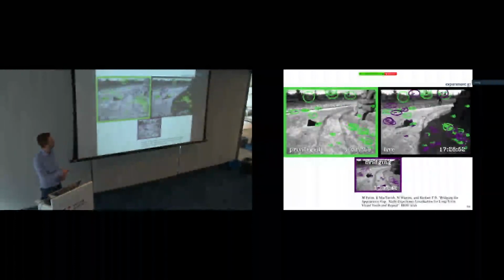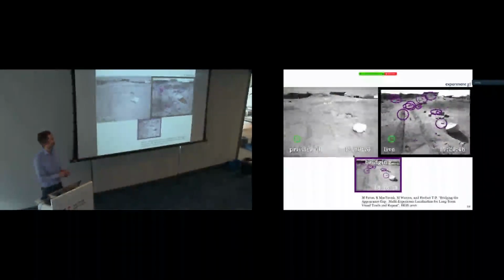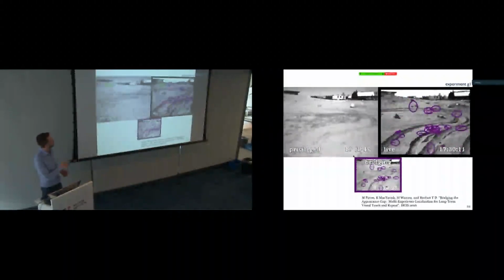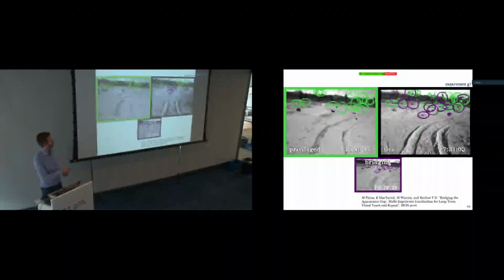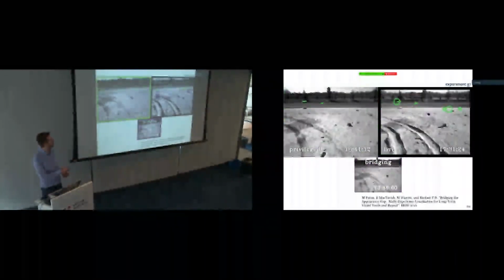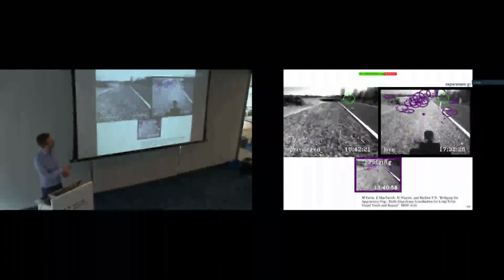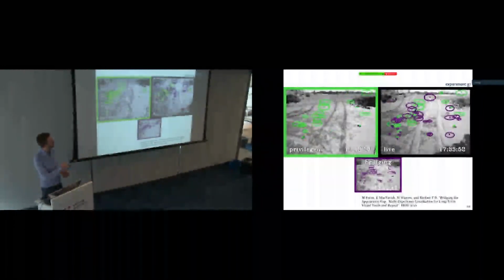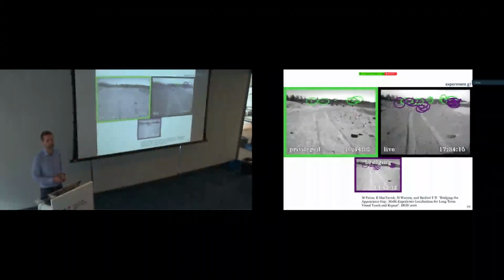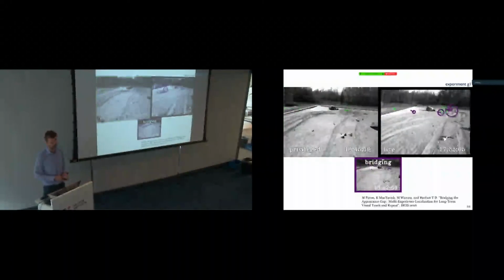And so what we do is we have this idea of having bridging experiences. So we teach the path, and this is the experience that's built into the map. Then 3.5 hours later, we drive and we see this experience on the bottom. We can probably match those things fairly well. And then all I have to do is take the later experience and match it to the bridging experience. And if I can get some matches back to the original experience as well, why not? So this is the idea of chaining things through time.